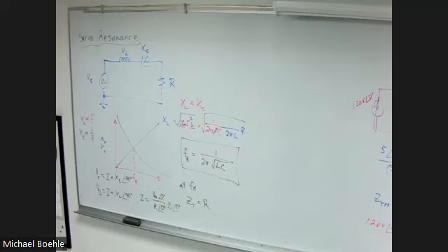So again, this is a unique occurrence. 0 degree phase shift. In fact, when it comes to doing the lab, the easiest way to find the resonance is actually just to look at the voltage across the resistor and the voltage applied and adjust the frequency until they're in phase. That's the easiest way to do it.